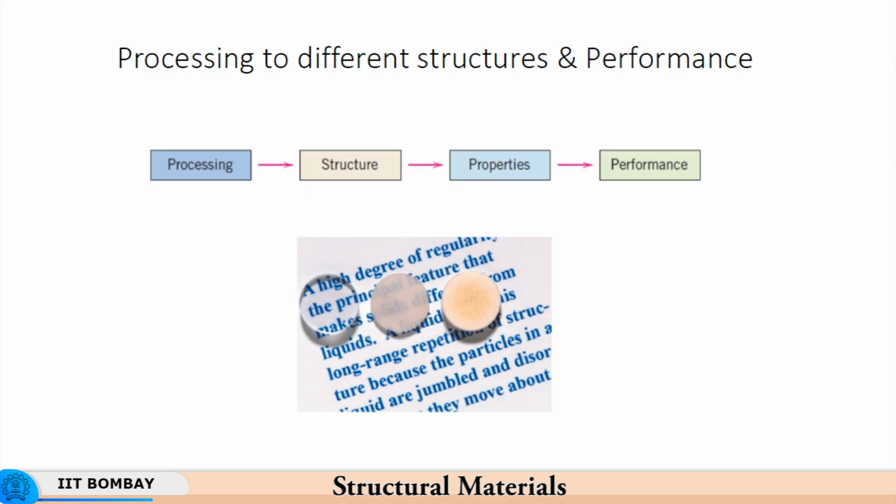Some materials do require this atmosphere. For example, magnesium, which is used in our sparklers and crackers, has an extremely high affinity for oxygen. If you melt magnesium and then try to pour it, it can explode, because it has an extremely high affinity to oxygen, and therefore you need to keep oxygen away from magnesium when it is being poured, particularly because it is extremely reactive under those conditions. So, you need to create an envelope of some other gas which would cut out the oxygen and prevent any contact of oxygen with that material, molten magnesium for example.